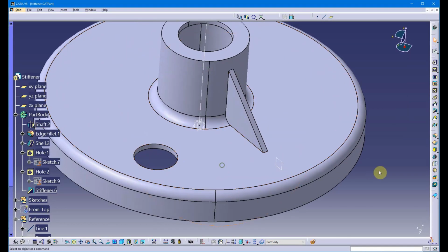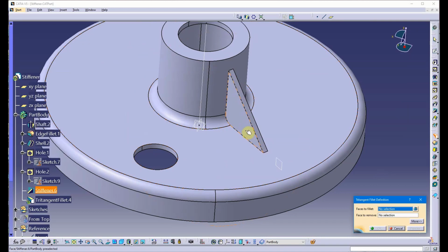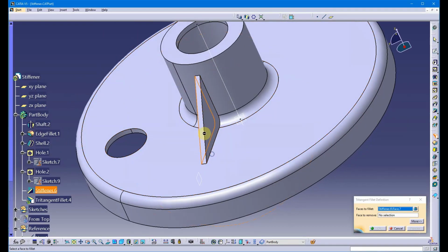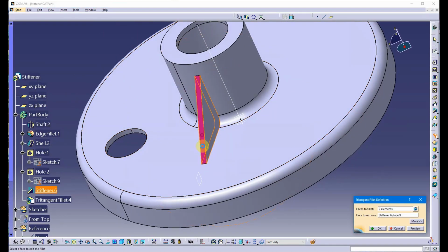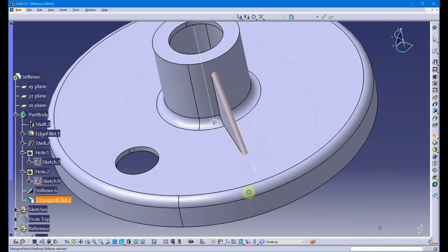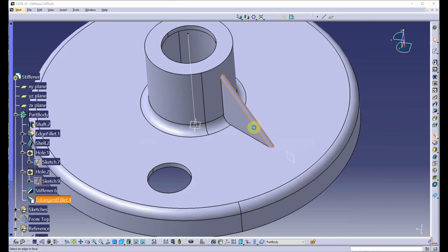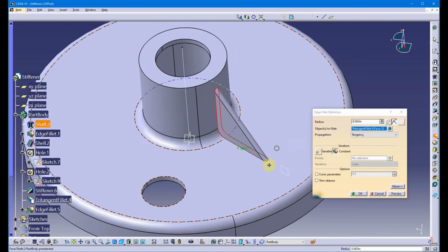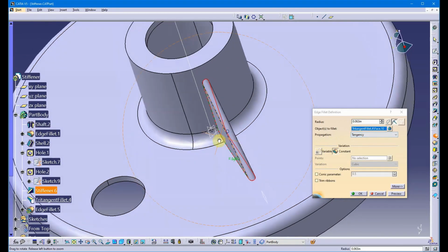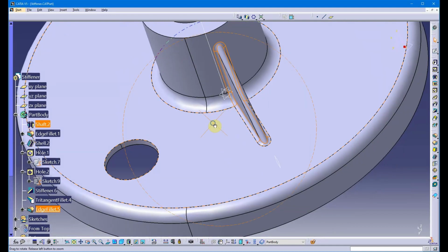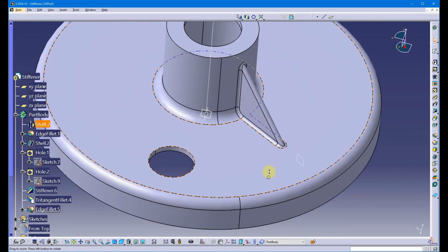And as before, I can throw in some fillets, such as tritangent, and throw in a regular face-to-face fillet. So it should propagate over if I've got tangent propagation turned on. That gives me some rounded stuff going on there.